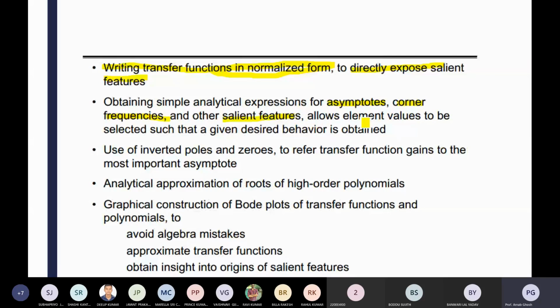For design purposes, how much rise time, settling time, phase margin and gain margin you want are further prerequisites. For my specific converter, I want that amount of rise time, that amount of peak overshoot, that amount of phase margin. There are direct relations between your time domain response and your frequency domain response.